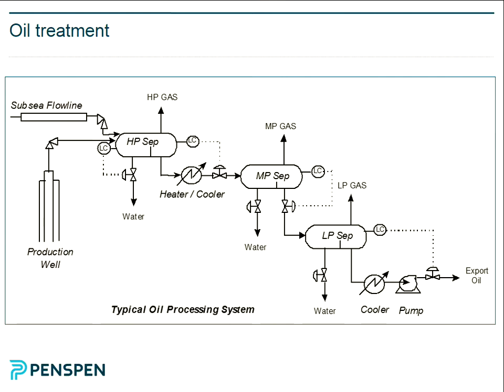And then you've got here a weir. So the water product's falling down into here. The oil and water are separating by gravity. So you can drain the water out here based on a level controller, and you can drain the oil out there based on a level controller. Obviously, then the gas is coming in here, and you don't want droplets. There's a chance you're going to get droplets of oil in the gas here, so you've got a mist extractor.